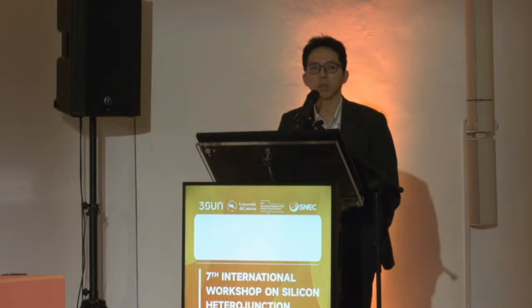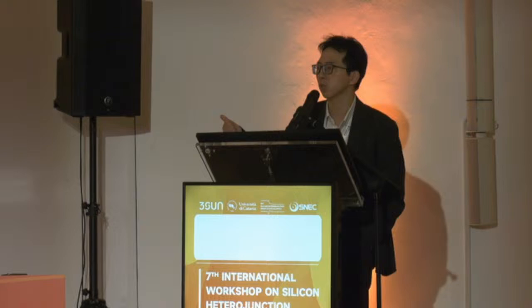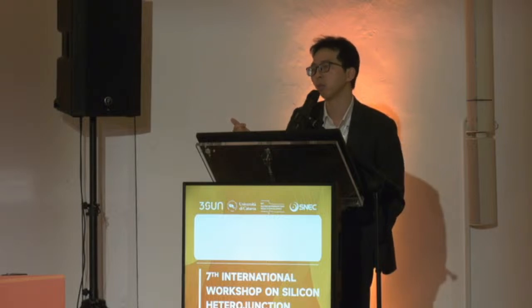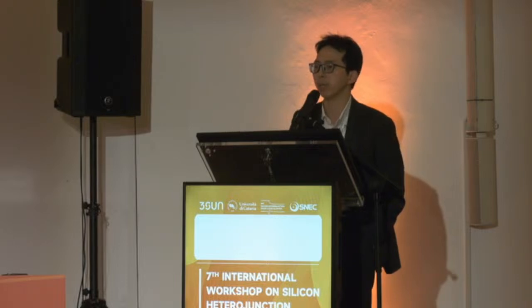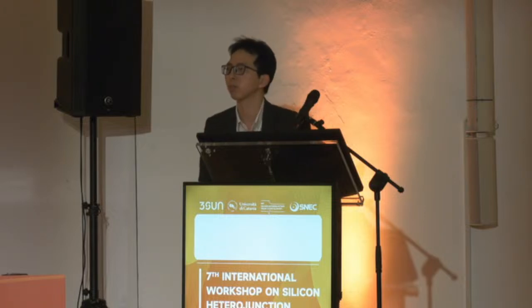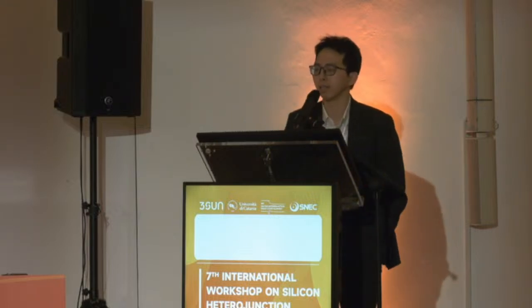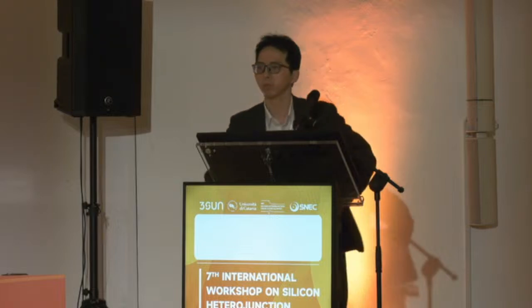I will say, because according to our test, this is not only a physical test, after the physical test, we also did some EL check for both models. And according to our EL test, the heterojunction one after this bending and recovering is still within IEC standard. Okay, so now when you compare say 90 micron and say 110 micron, in the production the mechanical yield loss was not too high for the reduced wafer thickness, if I understand? I think so, yeah. Okay, thank you.